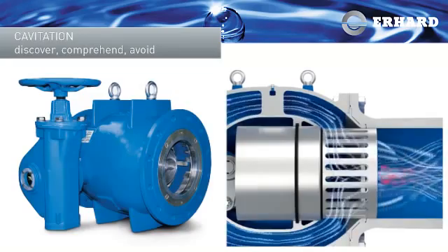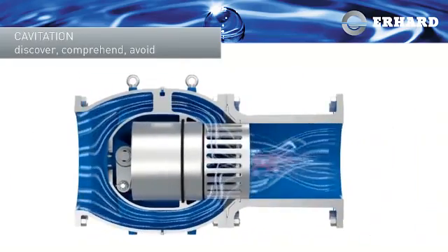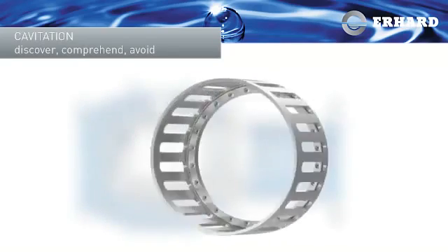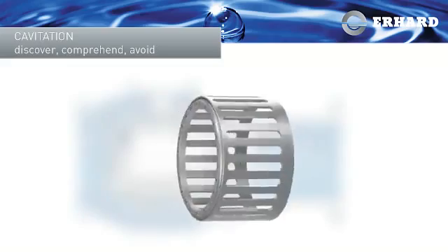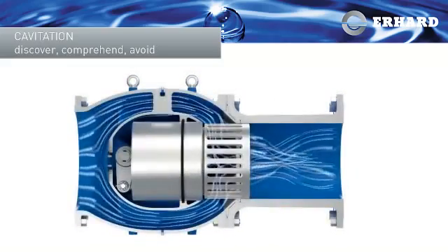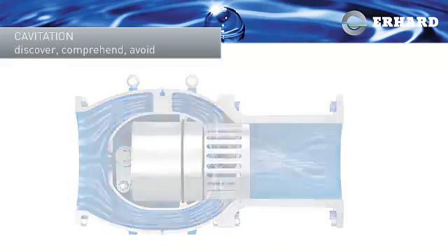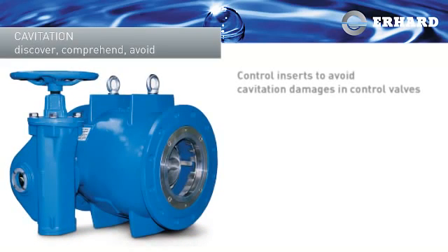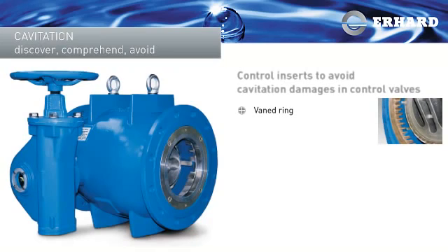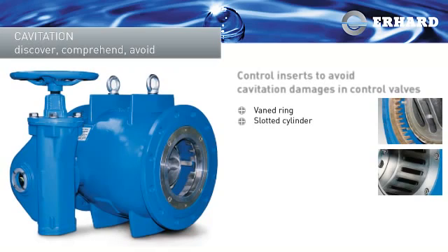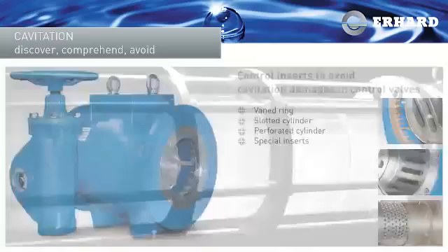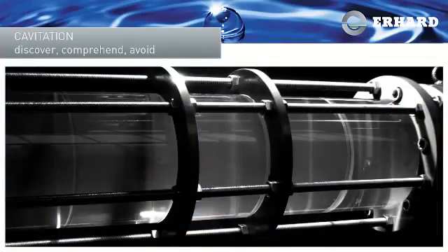Special control inserts, for example, ensure that instead of at the body wall, the cavitation takes place in the center of the pipe. It doesn't cause any harm there. Whether shut-off valve or control valve, ERHARD is guaranteed to have the right solution for you, and your ERHARD valve has a long life ahead of it.